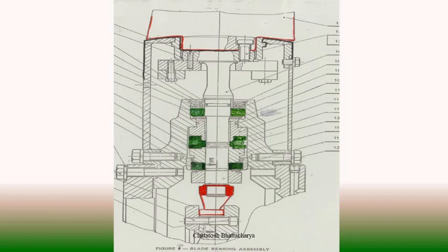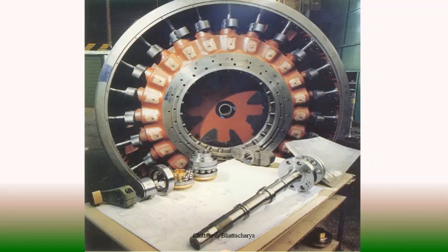blades are connected with an arrangement so that we can have a rack and pinion arrangement. With that, when they are rotating, all rotate together, and pitches are controlled at the same level. That means if one is rotating by 3 degrees, all the remaining blades are also rotating by 3 degrees this way. So this is the mechanism of